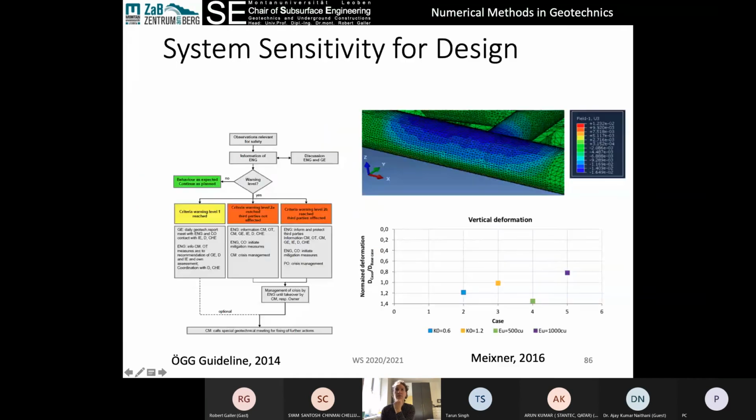visualizing those sensitivities. And then using sensitivity analysis for our design is not just for looking for the best design. So what happens if we make our rock bolts longer or our shotcrete thicker or whatever it is, but it can also be used for determining our monitoring thresholds. So if we have a deformation threshold warning level, so we say, okay, if we have deformations less than 5 millimeters, we're green. If we have 5 to 10 millimeters, we're yellow. 10 to 15 is orange. Greater than 15 millimeters is red.